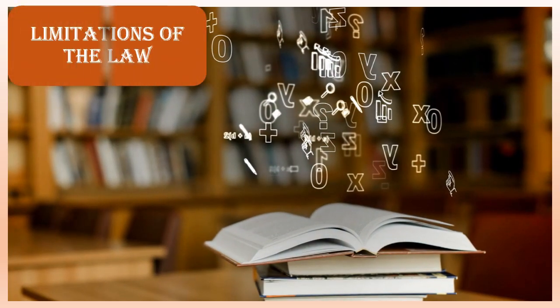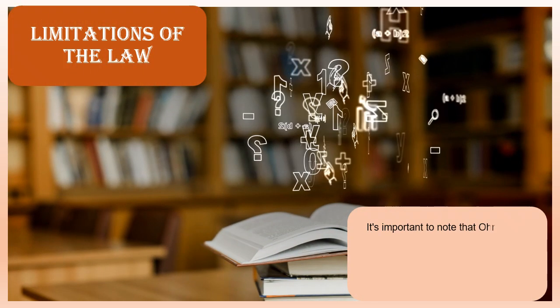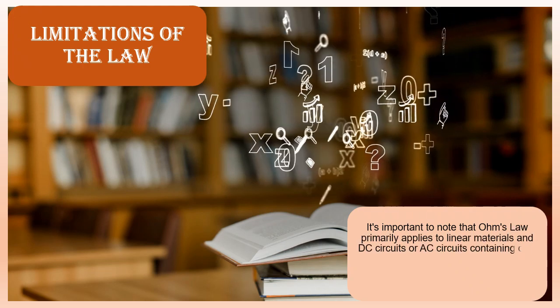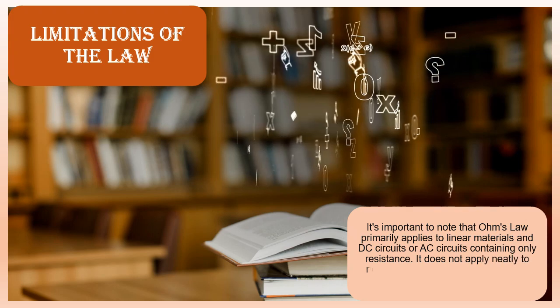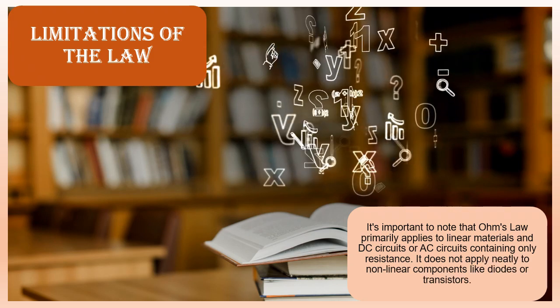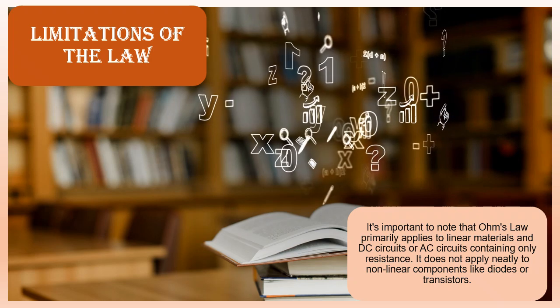Limitations of the law. It's important to note that Ohm's law primarily applies to linear materials and DC circuits or AC circuits containing only resistance. It does not apply neatly to nonlinear components like diodes or transistors.